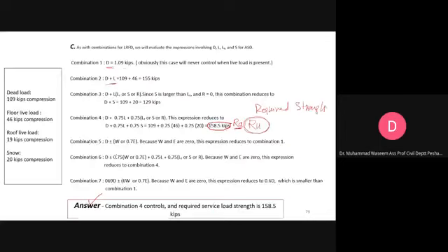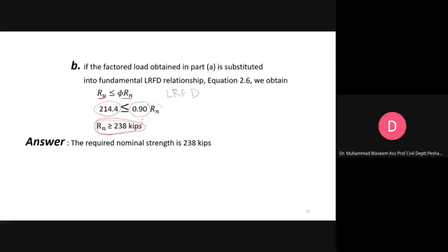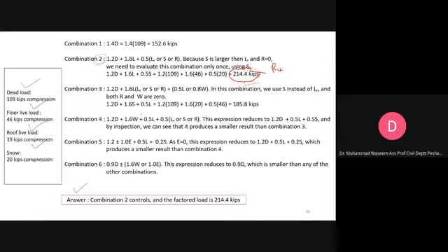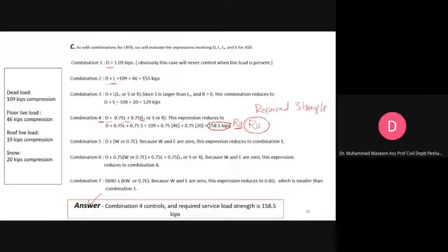It means that you will see that this is dead load, live load is controlling. And let's see in case of this, this is also controlling, the same combination is controlling, I think, dead load, live load, and S. Let's see. Dead load, live load, and S. The same is controlling. Okay.